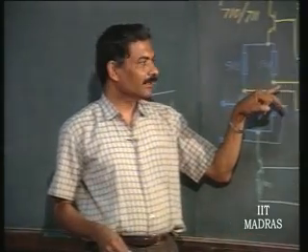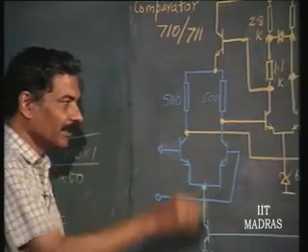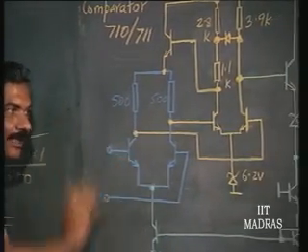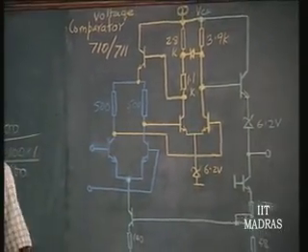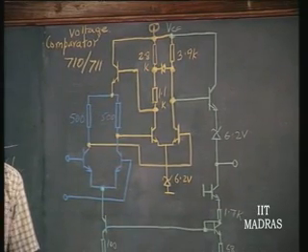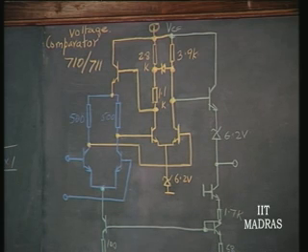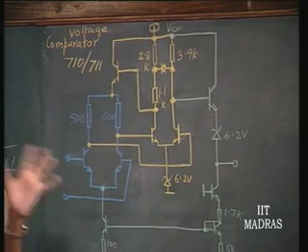This is a differential output stage. Let us carefully look at it. This input stage is feeding on to the next stage. What is the next stage? This structure? What kind of amplifier is it? It is not differential, it is common emitter amplifier, just as in the case of other op amps.